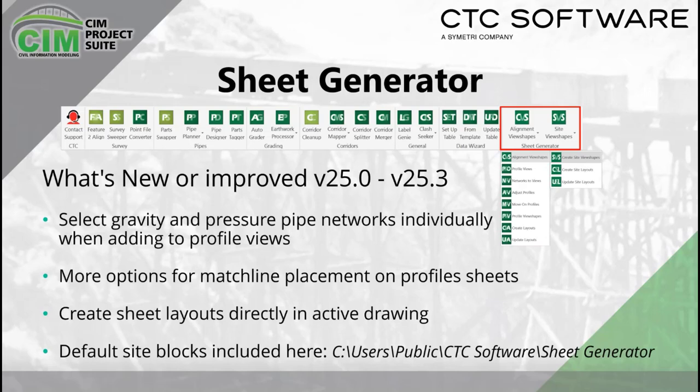And we have now added individually selecting of our pipe networks, including pressure pipes, to our profile views. And we've added a couple more options for our placement of our match lines on our profile sheets. And again, we can create our sheets directly in our active drawing.